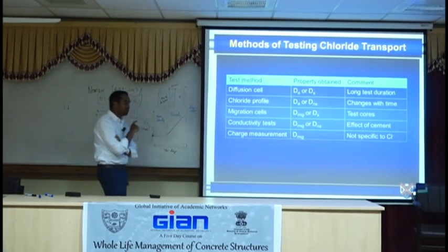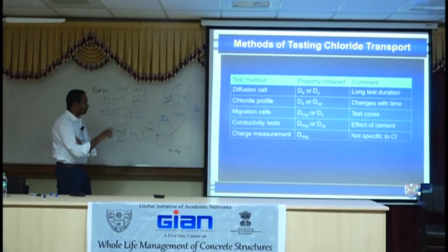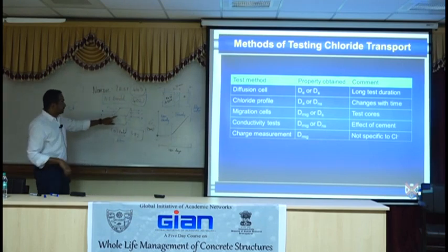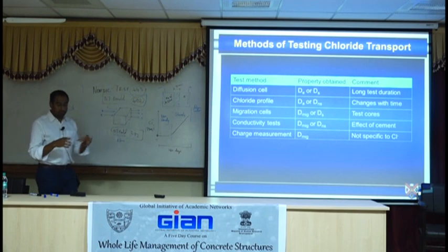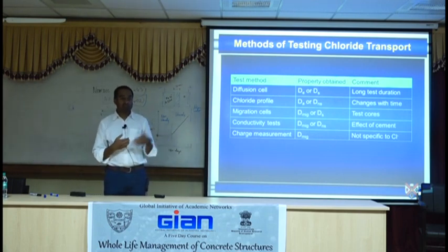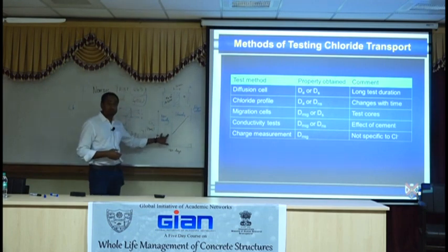There is a European standard which also relies on non-steady state. But it's very similar to putting a concrete disc into salt water and taking it out after 90 days and analyzing it layer by layer. Still measures in this region. It still gives you a diffusion coefficient.